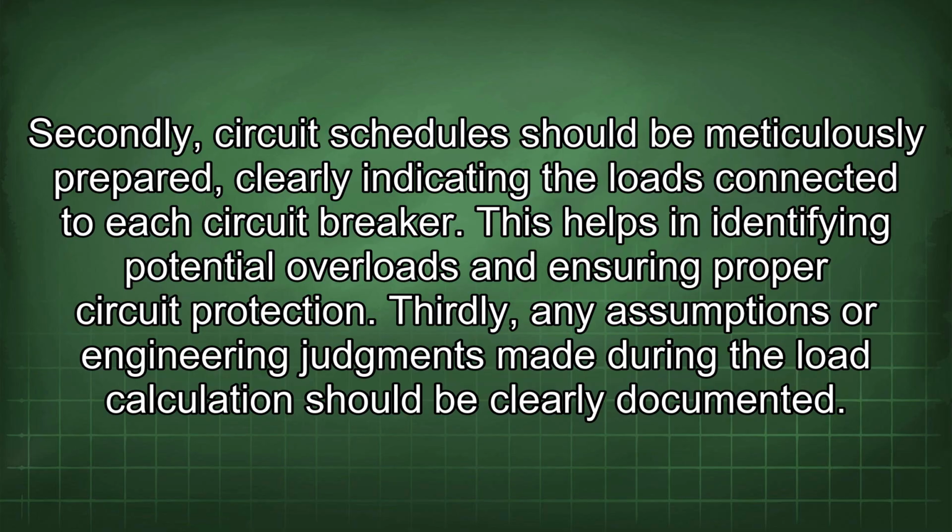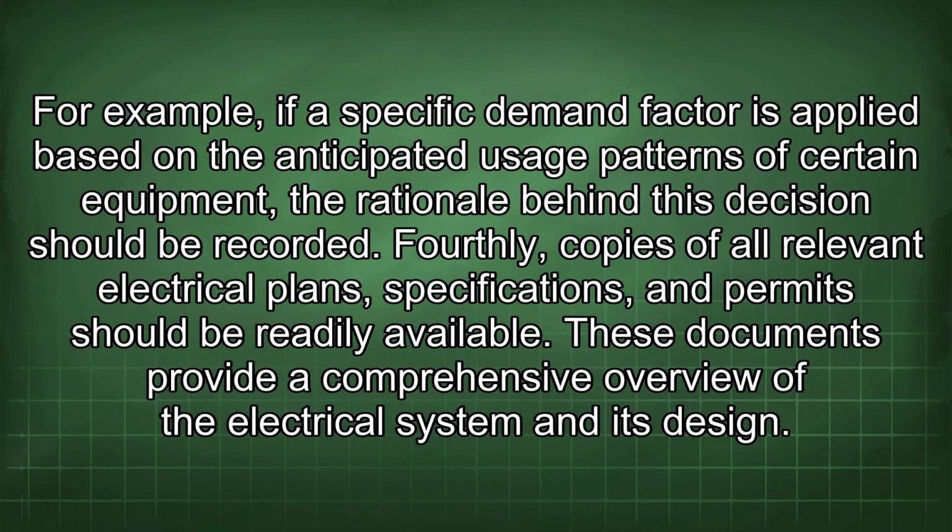Secondly, circuit schedules should be meticulously prepared, clearly indicating the loads connected to each circuit breaker. This helps in identifying potential overloads and ensuring proper circuit protection. Thirdly, any assumptions or engineering judgments made during the load calculation should be clearly documented. For example, if a specific demand factor is applied based on the anticipated usage patterns of certain equipment, the rationale behind this decision should be recorded.